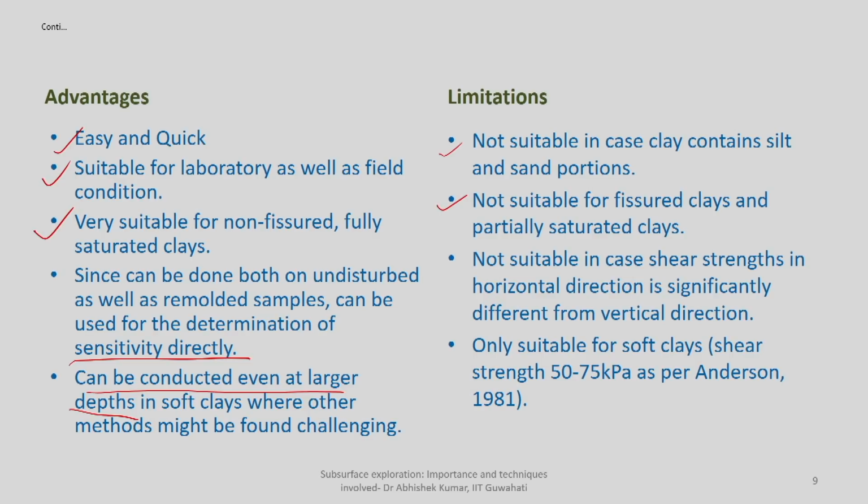And it is again not possible when the shear strength properties in the horizontal as well as vertical direction are significantly different, because as you saw in the equation we are using for determination of shear strength, shear failure happens both in the horizontal direction, because of the top and bottom plate, and in the vertical direction, because of the vertical edges.